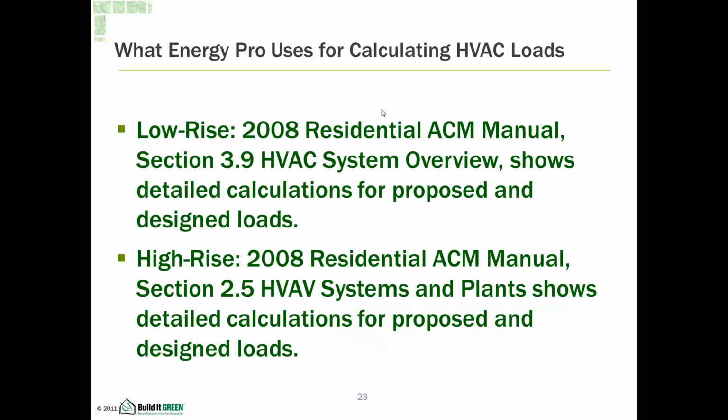Okay, so what Energy Pro uses for HVAC load calculations. The 2008 Residential ACM Manual, Section 3.9, HVAC System Overview shows detailed calculations for proposed and designed loads. For high-rise, the 2008 Non-Residential ACM Manual, Section 2.5, HVAC systems and plants shows detailed calculations for proposed and designed loads.